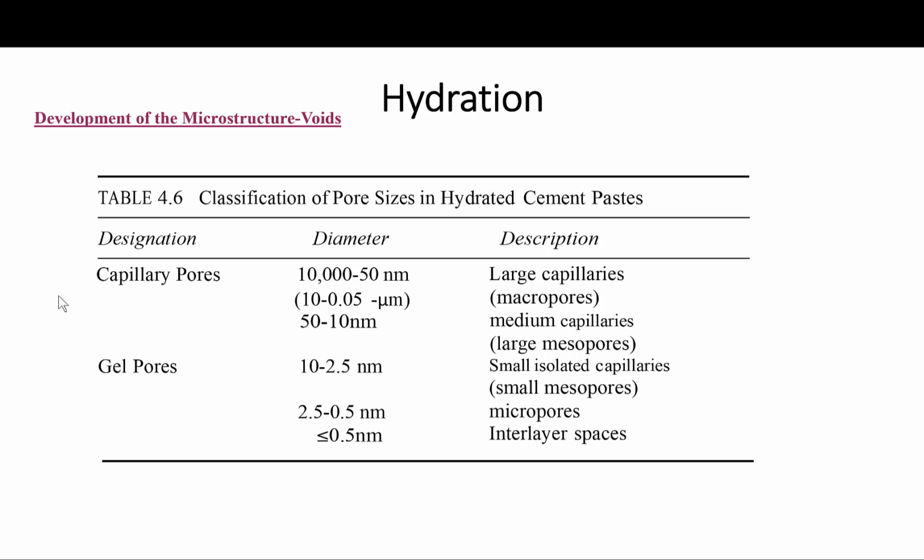The porosity seen in scanning electron microscope micrographs is the capillary porosity. The gel porosity cannot be resolved by the SEM and is included basically in the volume occupied by the calcium silicate hydrate. In mature pastes, the bulk of the porosity resides within the calcium silicate hydrate.